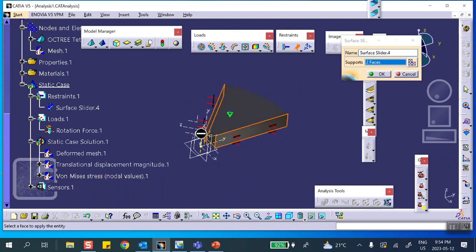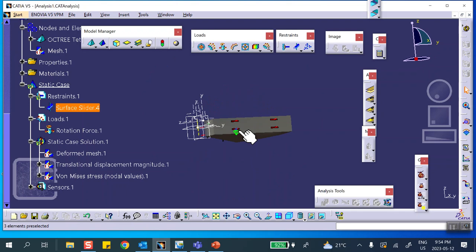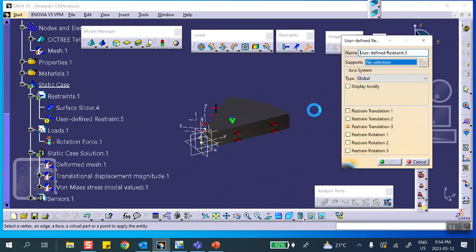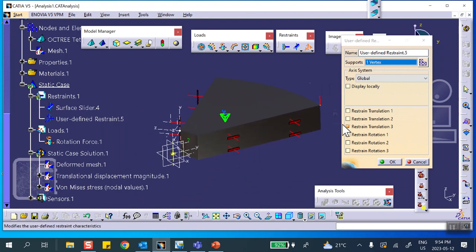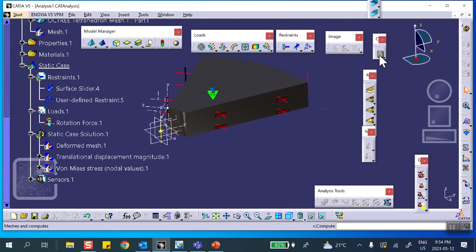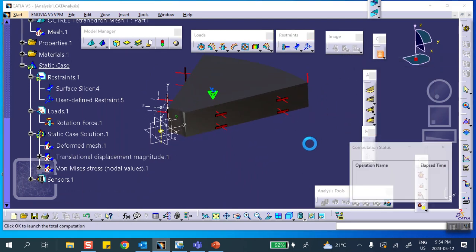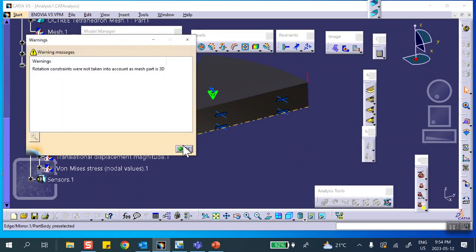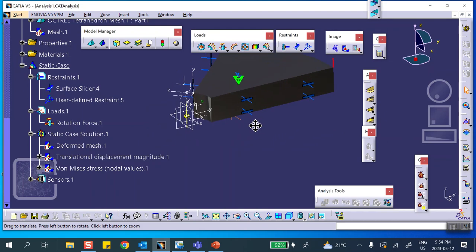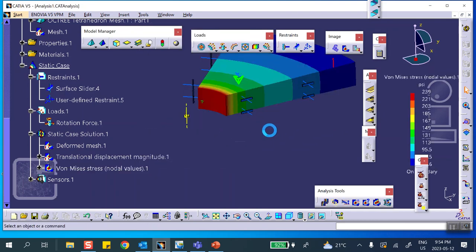I decided to do it all in one shot. Not the bottom, because the bottom is not planar symmetry anymore. And then user define in the global, with the global coordinates of a selected top corner point. In the global coordinate system, it's direction 3, right? Good. Run it again. Fine. Run, done. Right click, activate, same numbers.